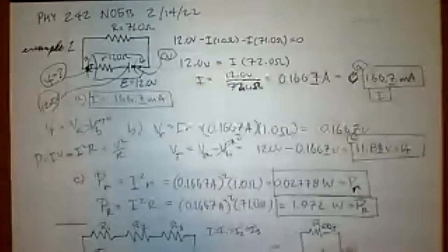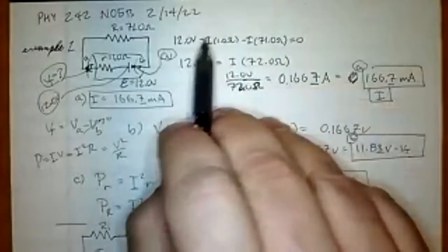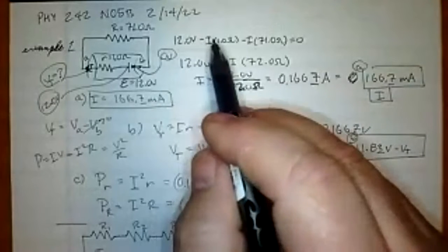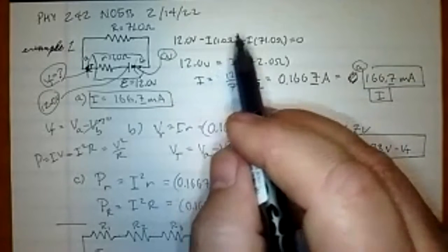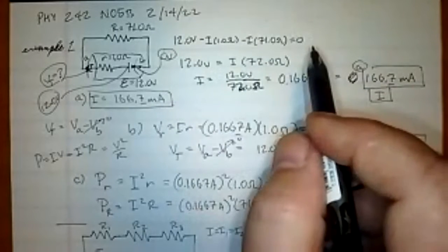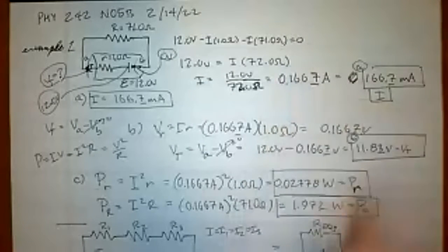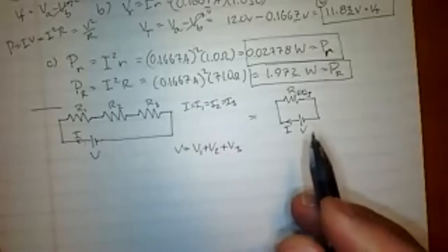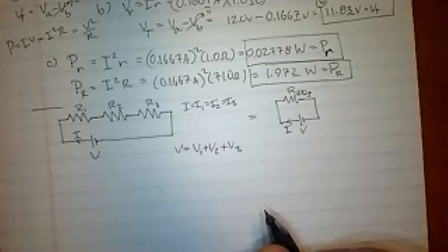What I basically did was the same thing I did here, but I put the minuses on the other side. So basically I'm saying the voltage of the battery minus the voltage of resistance 1 minus the voltage of resistance 2 minus the voltage of resistance 3 brings me back to 0. Only I put them on opposite sides. So hopefully everybody agrees with that.